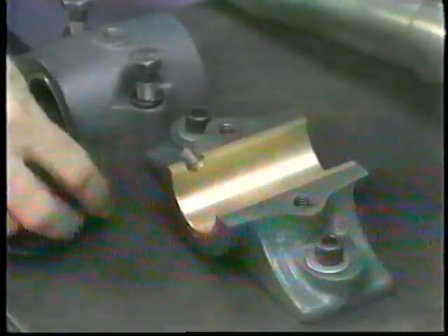If the edges of the bearing shell project slightly above the split housing surface, do not file them flush or try to shim the housing. The edges help secure the bearing in place when the housing is reassembled. Finally, always tighten the housing bolts to the correct torque.